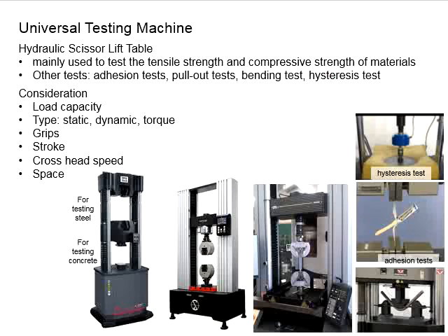The typical UTM here, which is the universal testing machine, will have something in couple, which there will be grips to the specimen you would like to test, and this grip comes in series of 2 sets, one at the top and one at the bottom, and it is very dependent on your specimens. You may use different grips for bars of different size, or when you want to test the plate, the grip will be different. Sometimes there will be a testing jig, something like this, for you to conduct the bending test, which can be installed to the UTM machines.